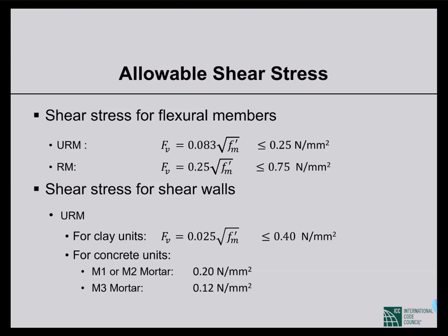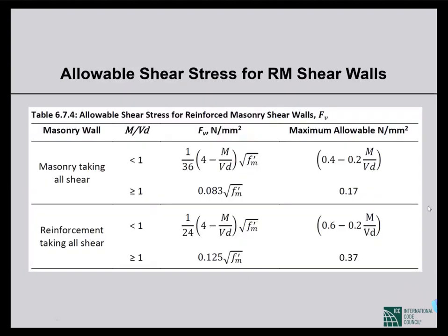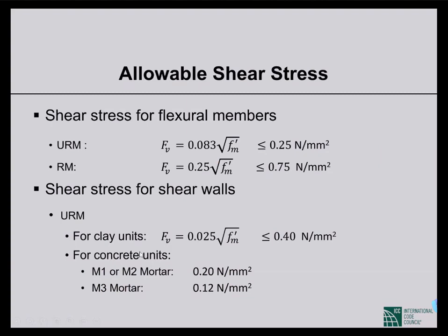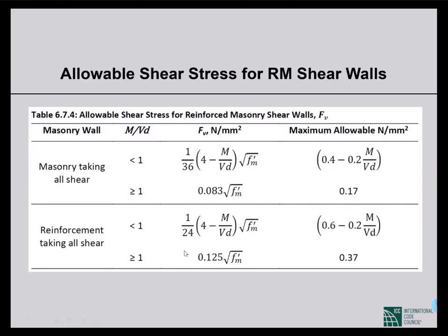Shear stress for shear walls, so in-plane shear, URM for clay units and for concrete units we have different values. Those were for shear walls. These are the values for unreinforced masonry. For reinforced masonry, it will depend on the in-plane moment divided by shear, divided by effective depth.